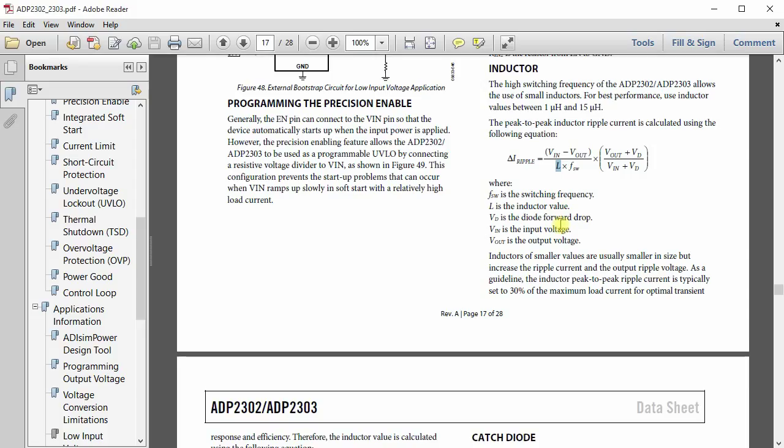What you, the engineer, have to determine is whether the ripple current value is acceptable in your application. Again, this is what I mentioned in the Handy Supply intro video regarding why it isn't possible to build a power supply that can be adjusted from about 1 volt to 5 volts, even if the divider network could be constructed, and it certainly could be, because the ripple current would get out of hand for a fixed inductor size.